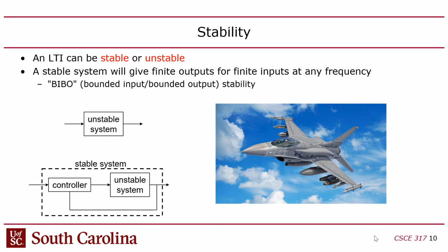So they have a control system incorporated that, when combined with the physical airframe and the physical control systems, makes it stable. That means some of the controls the pilot puts in have to be overridden and changed in a certain way before they go out to the control surfaces, in order to avoid this uncontrollable behavior.